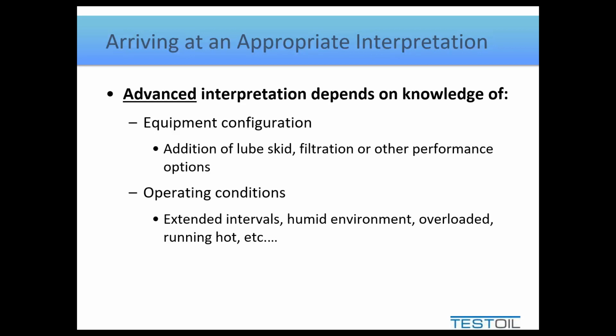Another factor is operating conditions. Is this thing being run at longer intervals? Well, it's hopefully fairly straightforward to think that the longer the oil is run, the more wear, contamination, and degradation you should see in that oil. So you may achieve higher and higher values than you've ever seen previously simply by going longer than you have. But if you don't tell the lab this, how will they know? And they start alarming your reports based on past history.